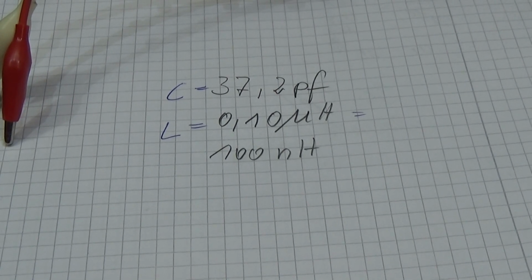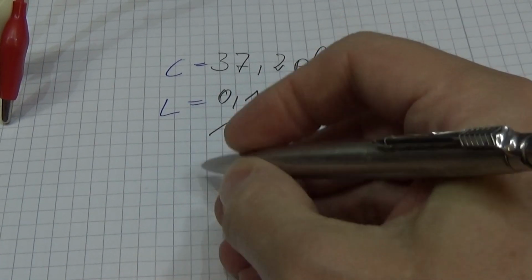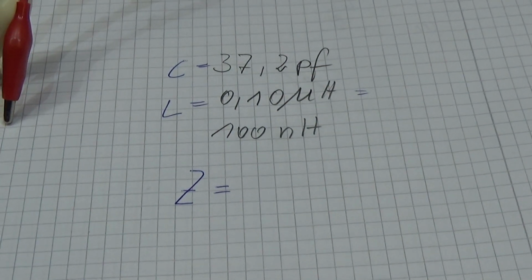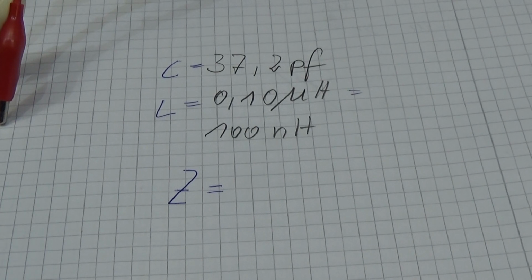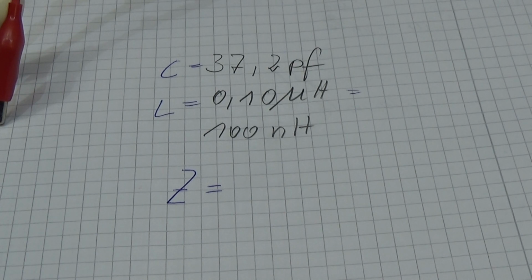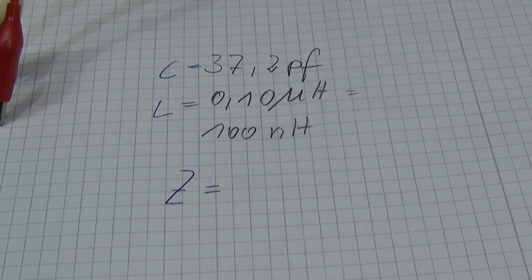And what we are looking for is our cable impedance. We expect, of course, 50 ohm, as it is a normal RG58 coax cable, a very well-known coax cable for our radio applications, and therefore we of course expect 50 ohm.